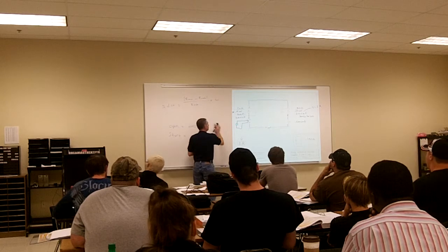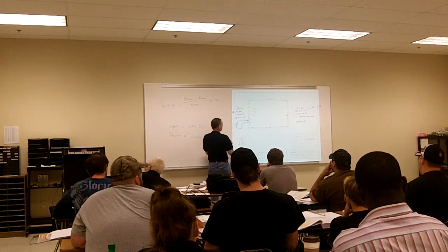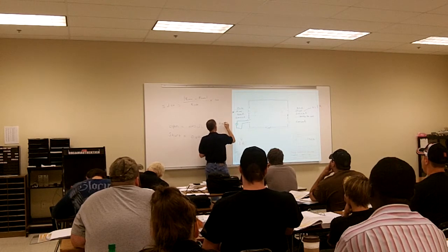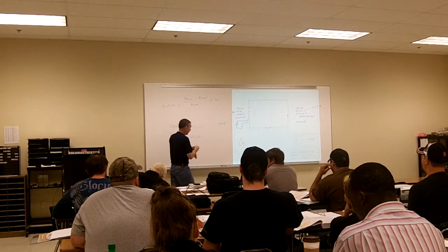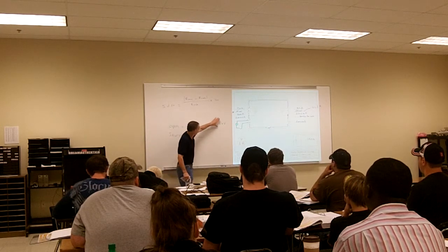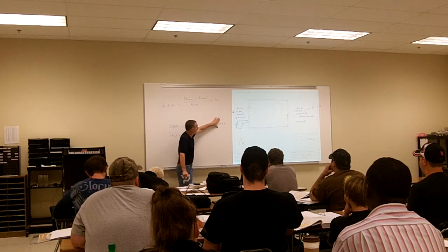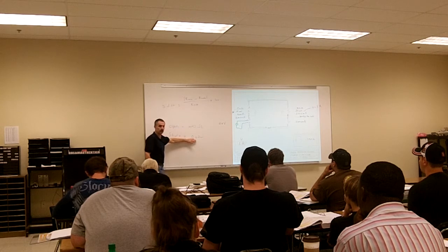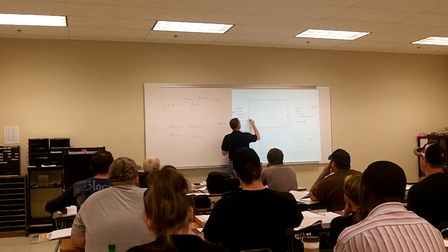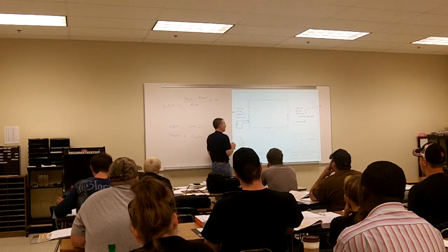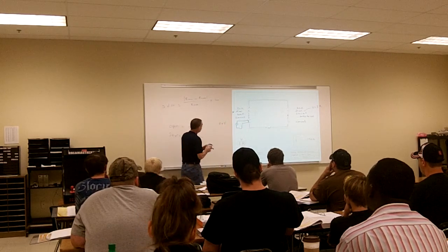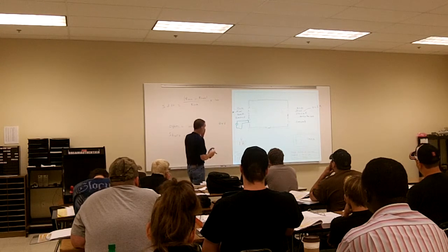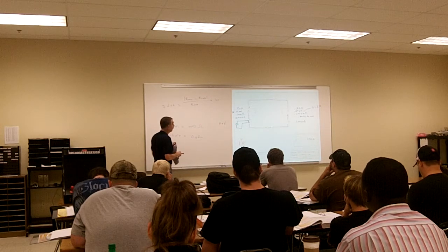Alright, so we're going to go back to the original thing there. We said that I'm going to be measuring 0 volts. So I ended up measuring 0 volts across there. So now I know that my fuse is what? Good or bad? Good. It's just like a short, right? It has 0 resistance. It means that it's just like a piece of wire in there. We don't even see that fuse in our circuit. It's just there to protect our circuit. So I have 0 volts going across my fuse. I identified that that's good. Then what would be my next step? What would I want to check next then?